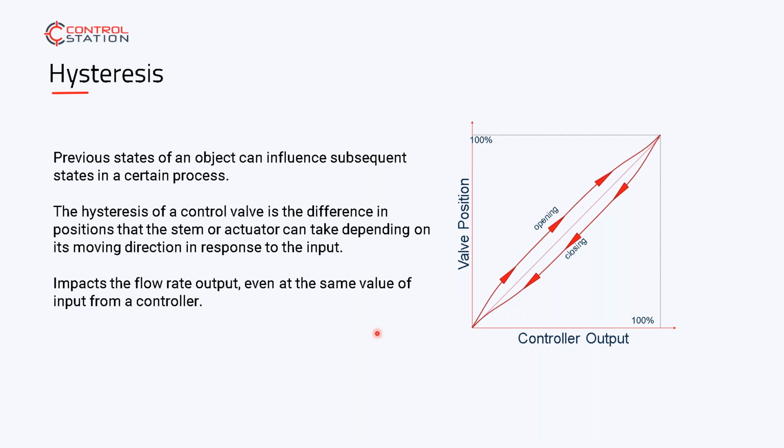It again can exhibit itself as positions based on where the valve is taken up, but typically, in my experience, I've seen it with systems where we've had high flow rates and low flow rates, or high pressures and low pressures, and the effect it has across the butterfly valves, particularly, you know, the lower quality, lower important systems will exhibit some of this more so.